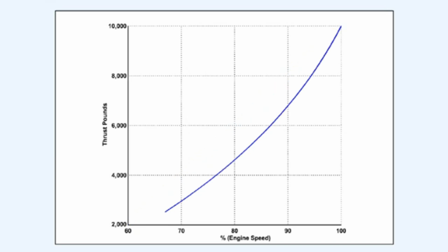Engines which have twin spool compressors have a slightly different relationship between RPM and thrust developed. This happens because optimum compressor blade efficiency and compressor ratio are designed to occur at higher RPMs that are normally utilized during the cruise, where the engine spends most of its working life. The relationship between RPM and thrust becomes non-linear, as shown in this diagram. This diagram illustrates that the highest 30% of the thrust is obtained with the RPM above 90%.